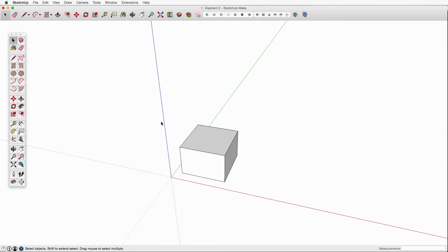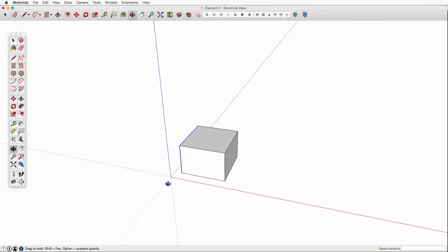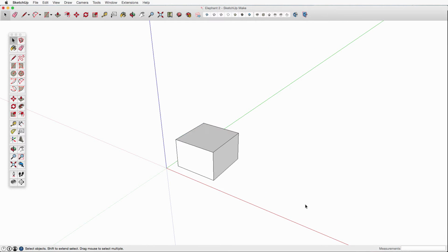Or I could select part of the box. Okay, so this is click and drag. And there's also a different way to select, which is clicking and dragging from the lower right-hand corner, which selects differently. It's called a crossing box. So as long as I've crossed something, I've selected it, whereas on this one, I have to enclose it to select it. Two different things. Check the videos if you're curious about that. But I'm going to triple click and then just hit delete.